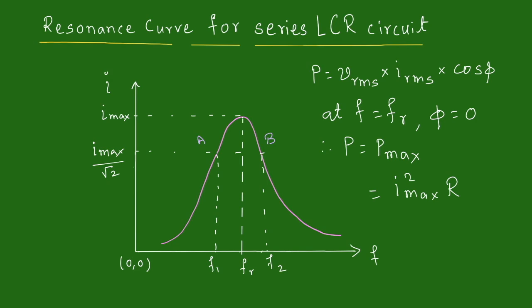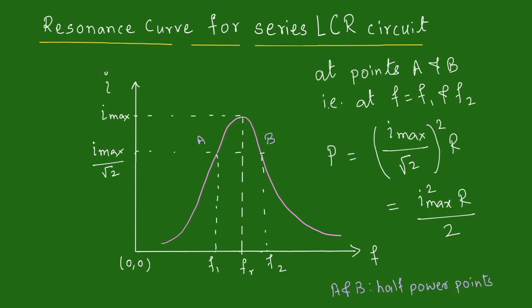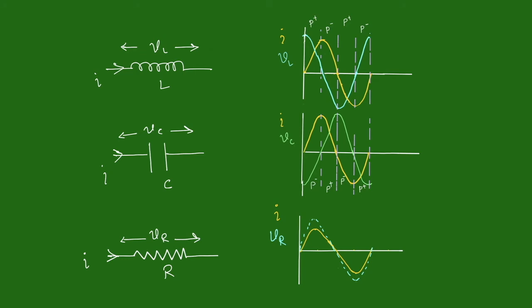Over a complete AC cycle, the power consumed by a pure inductor as well as by a pure capacitor is always zero. Why is the average power consumed by a pure inductor or a capacitor over one complete AC cycle always zero? As we have seen earlier, in the case of a pure inductor as well as a pure capacitor, the current passing through it is out of phase with the potential difference across it by 90 degrees.